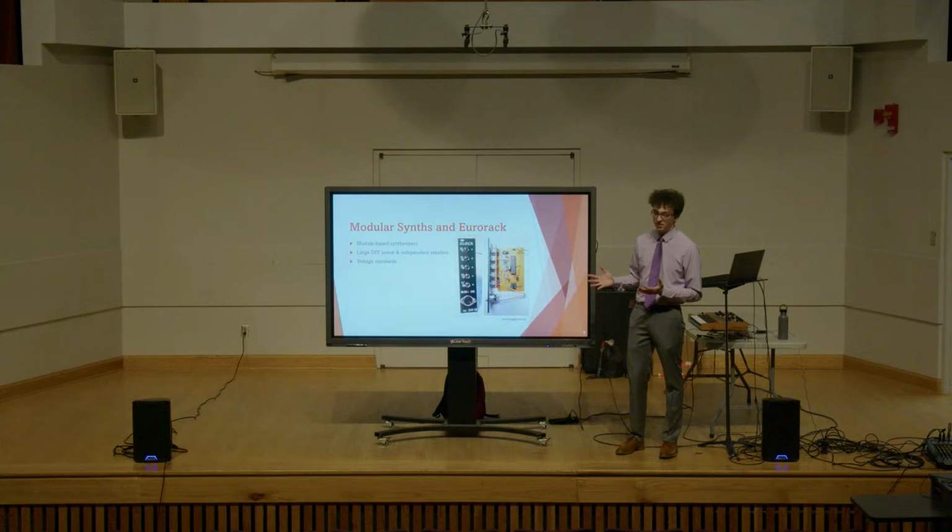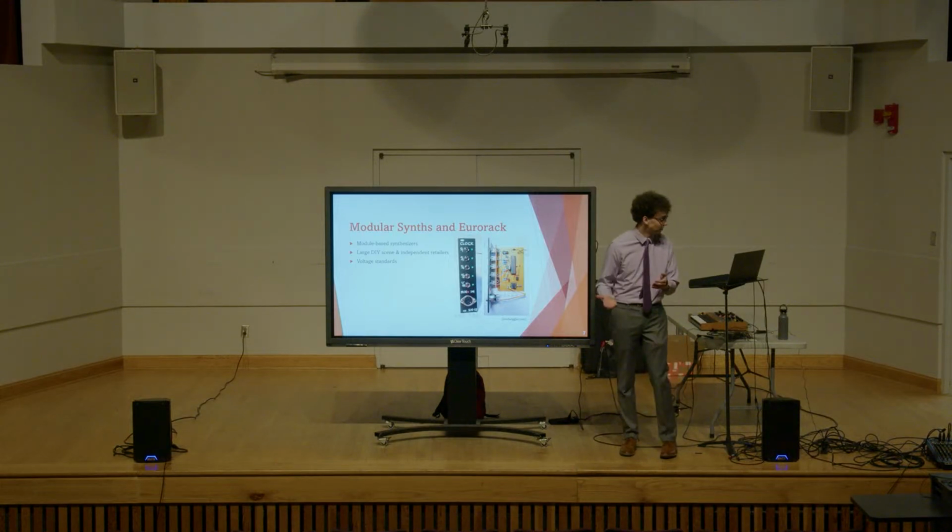And these all generally adhere to the Eurorack format of voltages. It's a standard that defines power as plus minus 12 volts, maybe plus 5 volts. It defines your output waveforms as probably plus or minus 10 volts peak to peak. So it's that sort of standardized system that ties everything together. And so a lot of what you're going to see from me also happens to fall into that because of where I've taken my schematics from.